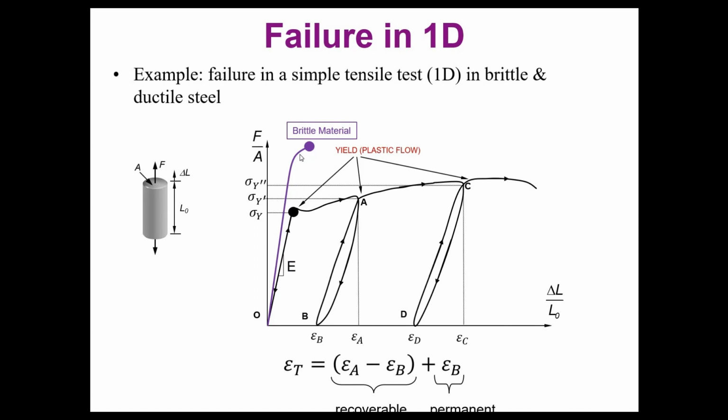In the brittle material, it's not necessary because these strains are very, very small. And because you are going to recover almost all of them, you don't need to define anything before the failure, because at the stage of the failure, in terms of load and strength, you will still have an elastic behavior.